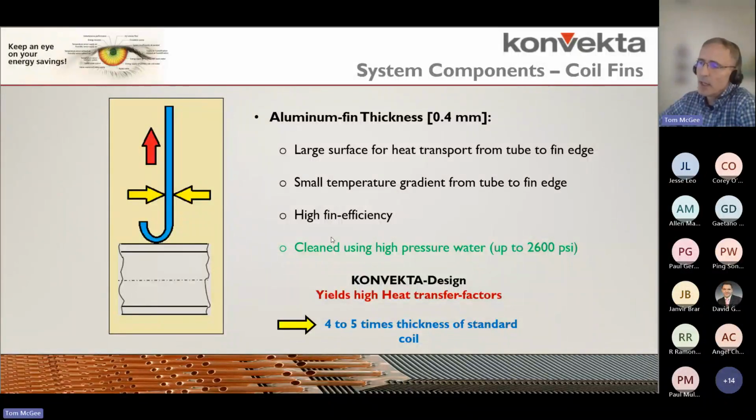But we install our coils in exhaust air streams in a lot of instances, and there's a couple applications, one of which is snow melt, which of course the snow melt coil goes upstream of a coil bank. So you're not filtering the air that's coming into the inlet of that coil, but we're able to do that and apply the coils in that fashion, in large part because of the ability to effectively clean those coils if they do get dirty.